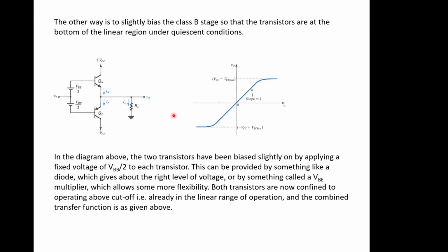So if you put those two characteristics together, you've actually squashed up this crossover distortion point, and if you get it right, you get a completely straight line through here, and there are no instantaneous changes of voltage hidden in there or anything. So the clever bit becomes, how do we set these voltages and then add our signal voltage to it?